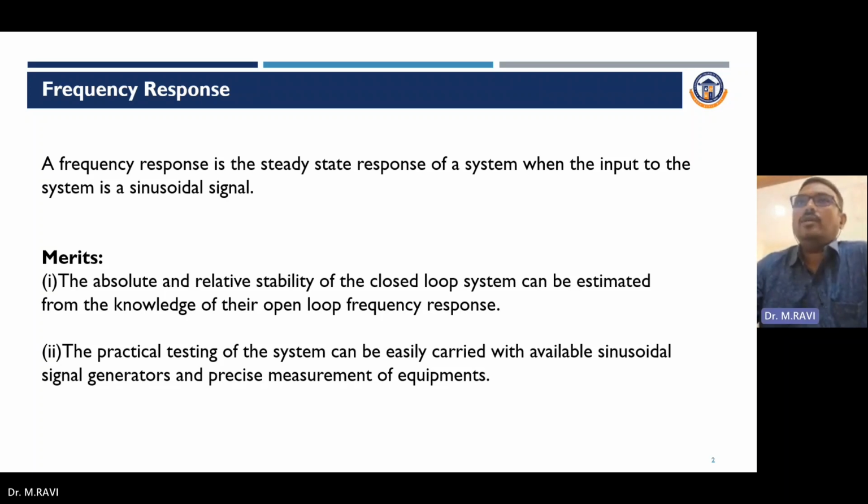The merits of frequency response: First, the absolute and the relative stability of the closed loop system can be estimated from the knowledge of the open loop frequency response. Second, the practical testing of the system can be easily carried out with an available sinusoidal signal generator and precise measurement equipment.